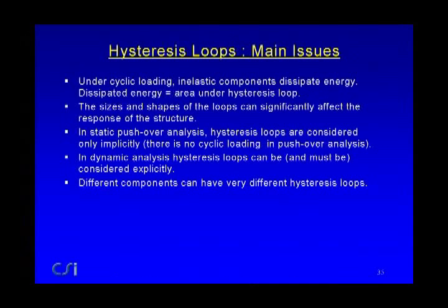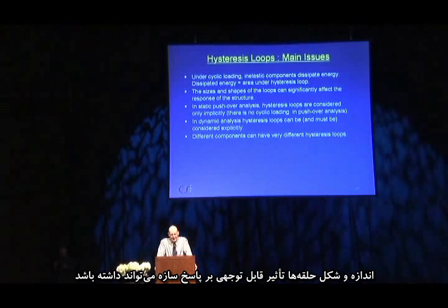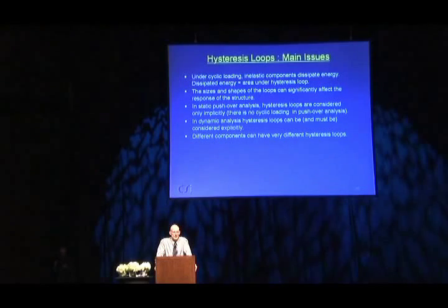Under cyclic loading, the inelastic components dissipate energy, and the dissipated energy is simply the area under the hysteresis loop, or the sum of the areas under all of the loops. And the sizes and the shapes of the loops can significantly affect the response of the structure.